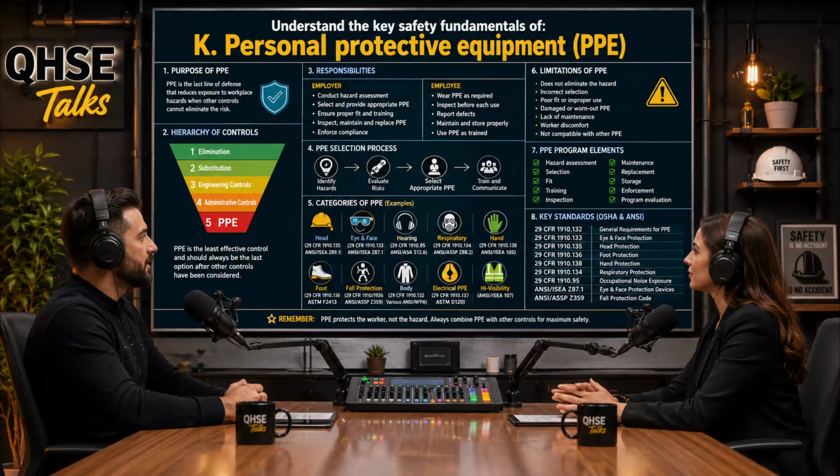The engineering behind that fabric is remarkable, but again, human behavior is the weak link. How so in this case? If a worker wears a 40 cal/cm² arc flash suit, but they leave the top button undone because they are hot, the plasma wave will instantly seek out that vulnerability, flow inside the suit, and the protection is negated.